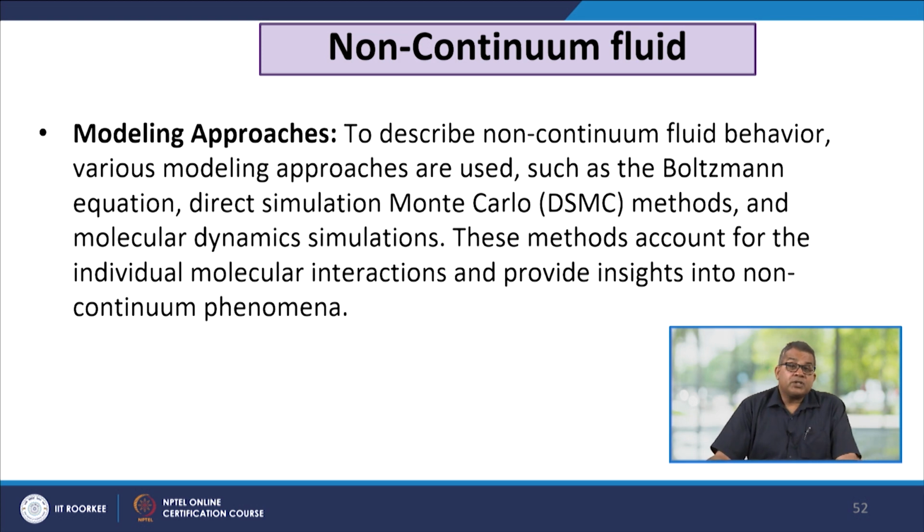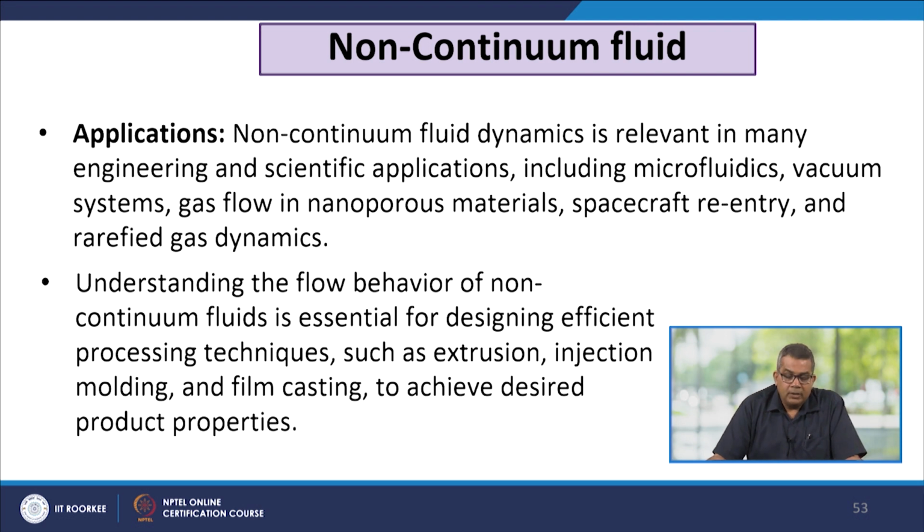The modeling approaches. To describe the non-continuum fluid behavior, various modeling approaches are used, like the Boltzmann equation, direct simulation Monte Carlo methods and molecular dynamics simulations. These methods account for individual molecular interactions and provide insights into non-continuum phenomena. The various applications: non-continuum fluid dynamics is relevant in many engineering and scientific applications. This includes microfluidics, vacuum systems, gas flow in porous materials, spacecraft re-entry and rarefied gas dynamics.